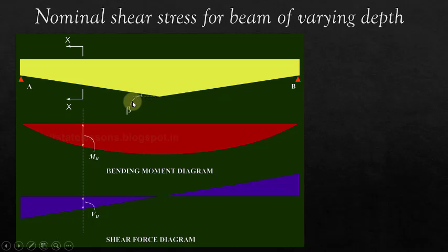We know that whatever type of loading, that is UDL, uniformly distributed load, concentrated load, uniformly varying load, etc., acting on the beam, for that we can calculate the factored bending moment Mu and shear force Vu at any section XX on the beam.